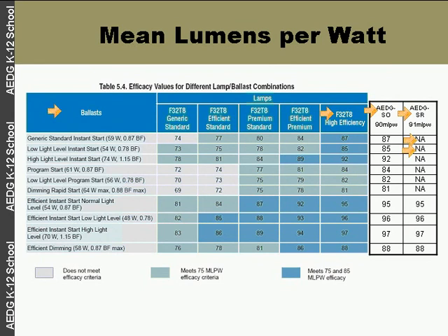The high output lamp, you can basically use half the number of lamps that you see in a T8 system. So you get fewer lamps up there. Optically, the fixture becomes more efficient, even though if you were to look at lumens per watt, it's a little bit lower. So here's again the breakdown of what we see. We're seeing that the general warehouse makes up about 75% of the floor area. We dropped the lighting power density to 0.6 watts per square foot. We also have a fine storage area that we're assuming takes up about 20% of the floor area.